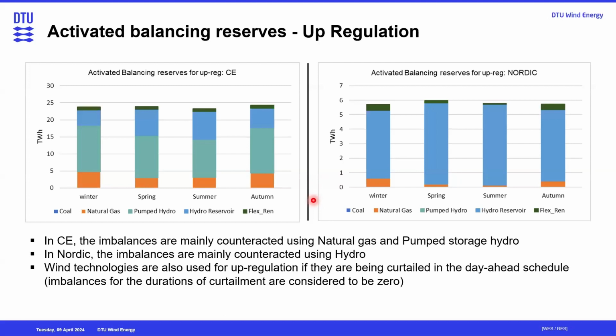And then we already discussed the forecast error, right? So these are the two sources of imbalances which can be prognosed, whereas there are other imbalances coming from contingencies, which is out of scope because they are completely random, completely stochastic. You just superimpose that after you have done these studies, saying I need this much for the contingencies.